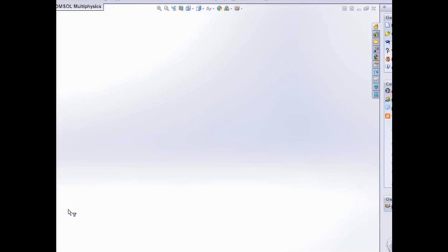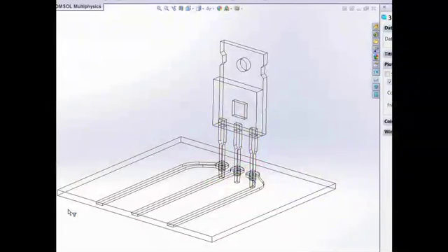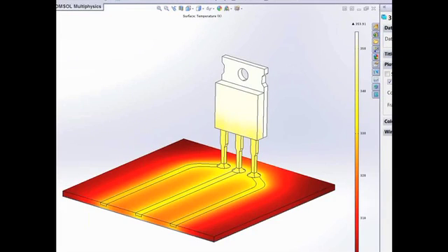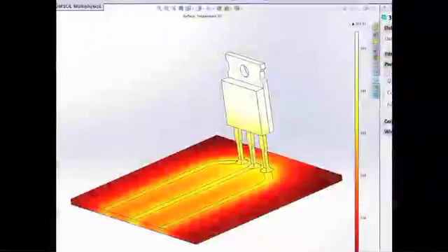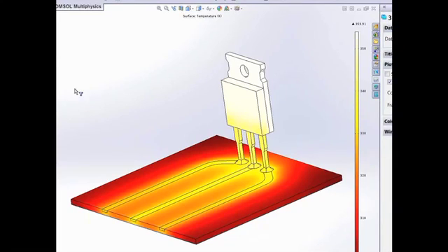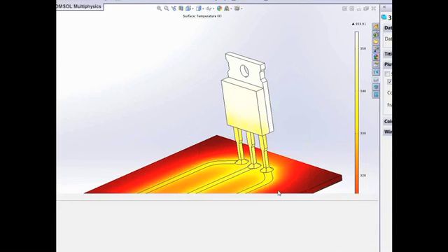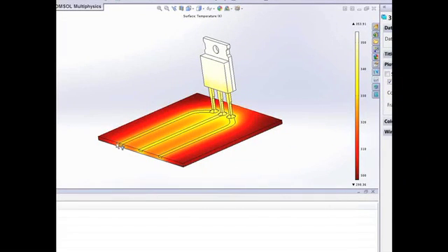And when I open this, I would just show you real quickly a little bit about how post-processing works, and that will be the last part of this demo. So as you can see here, we can see the temperature field in the model, which means that I've already solved the physics that was set up inside the model. And here I can quite easily just click somewhere in the graphics window to get a temperature reading in a table, in the COMSOL results table.